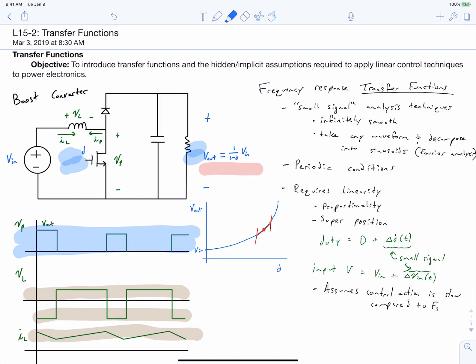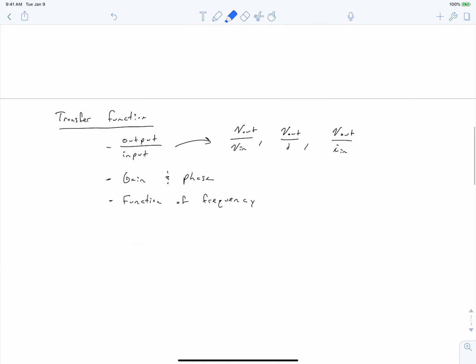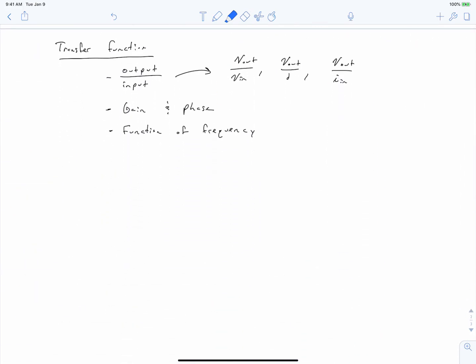So we can sweep that variation in our input over some frequency range and observe the result of the output, and we can capture this within the transfer function. So the point is that you have two ways of determining your transfer function. The first is that you calculate it explicitly, and the second is that you measure it. And oftentimes you may do both to validate a system.